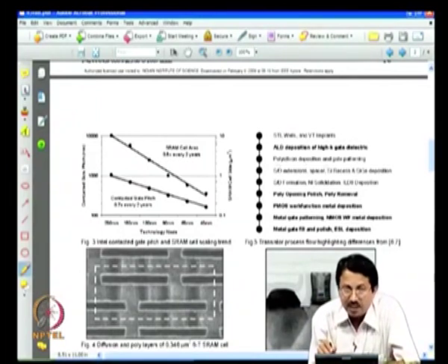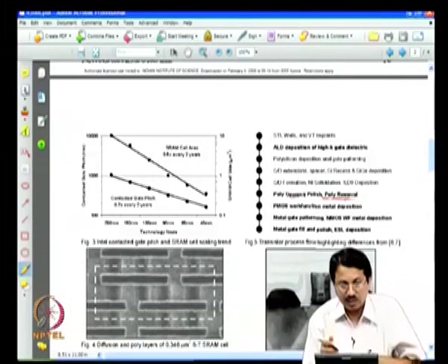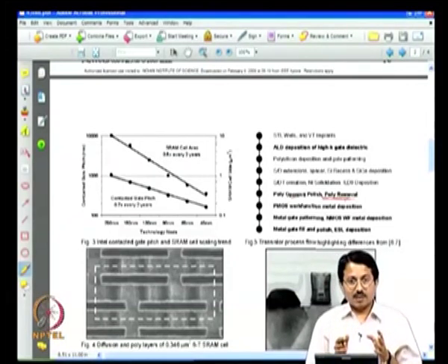So, polysilicon is done as usual, gate patterning, source drain extension, spacers, everything is done, source drain formation, nickel silicidation, and then you deposit an insulator. Then poly opening, you etch back the poly, poly is removed. That is what we mean by disposable metal gate. Poly was sitting there as a placeholder, so that you get self aligned transistors.